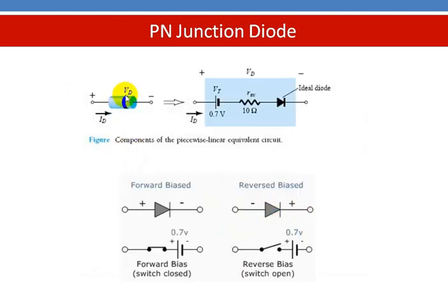So this is the diode. Vd indicates the forward voltage drop. This ring indicates the cathode terminal. So this is the equivalent circuit. The diode has a threshold voltage, or cut-in voltage, of 0.7 volts for silicon, and this material also has some resistance, close to 10 ohms. The voltage across the diode is called Vd, and in some cases it is called Vf.